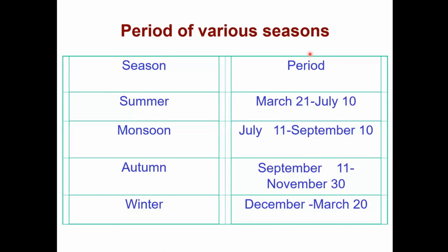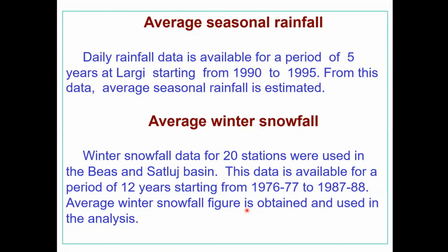But the seasons were fixed depending upon the hydrograph. That means when snow melt starts, when the hydrograph is changing, when suddenly the hydrograph is going up because of the monsoon precipitation, when the hydrograph reduces once the monsoon has retreated, and when snow accumulation starts, when it reaches the base flow, how minimum the stream runoff is. So basically by using the hydrograph, it is grouped into 1, 2, 3, 4 seasons in the Himalaya.